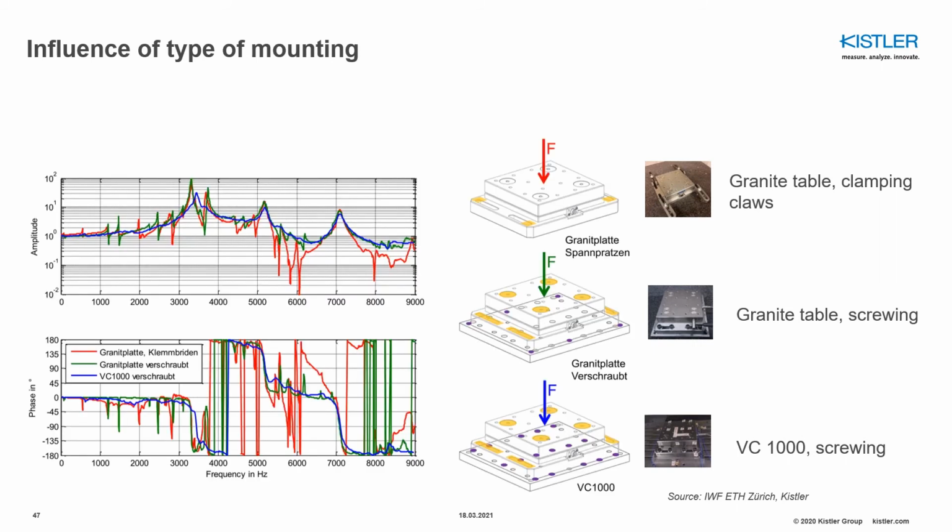And if you look to the now, when the force is excited in the zeta direction, the frequency response of our system, depending on this different type of clamping, will be different, as you can see in this plot here. And then you have the phase shift, can be seen here. So it's really important to understand the response of your system, and it is depending on the mounting, of course.